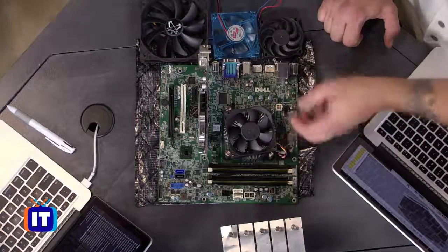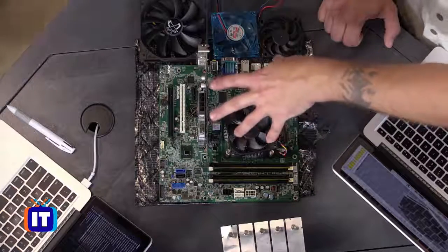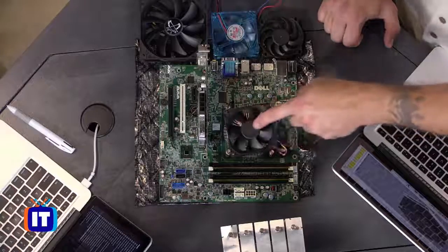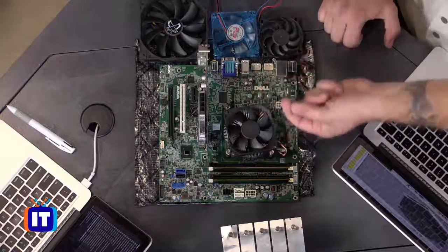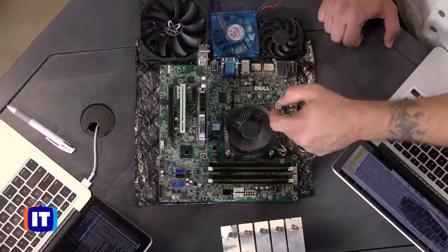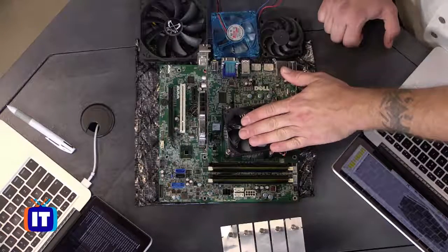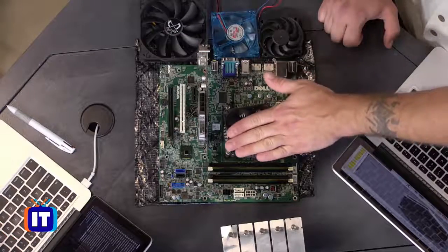Keep in mind that it's typically connected to the motherboard, and that's something that you want because the chipset, and really the BIOS or the UEFI system, can actually detect the core temperature of the CPU, and as that heat rises, it can apply more voltage to this fan and increase the RPMs within the fan. Now, that's not the only thing we have. Remember I told you that the system unit also has system fans as well.